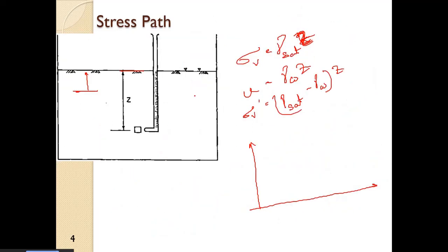Now suppose we have here, so this was the failure surface. All right, so tau is equal to C plus sigma n dash tan of phi dash. All right, so we had the total stress Mohr circle here, right? And initially the groundwater table was here, suppose we considered. All right, so this is the groundwater table. So we had the Mohr circle, effective stress Mohr circle here.